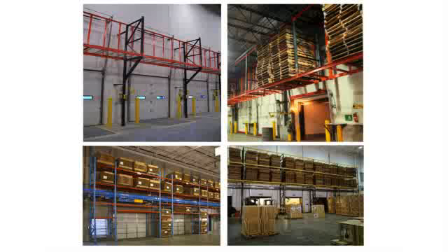In the top left-hand picture of the slide, you will see the storage racks attached to the building columns, and in the upper right-hand side, you'll actually see the racks hanging from the roof ceiling. Both of these, the loads themselves have to be taken to the designer of the building to confirm that the building is designed to absorb these kind of loads.